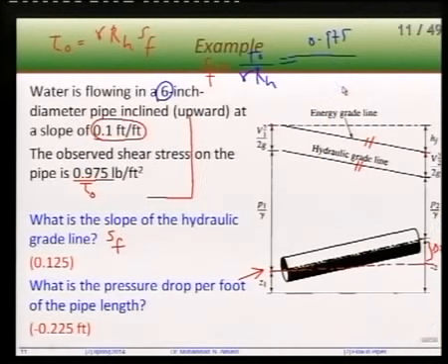So this is half foot. So this is the hydraulic radius in foot. Now, the specific weight, how much? 62.4. Please do not make that mistake and put whatever in Newton per cubic meter. So this is pound per cubic foot. Then you can find SF.